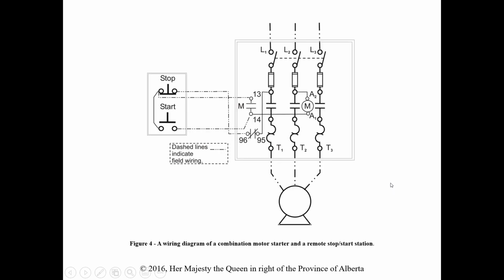Then we talk about a wiring diagram. The difference with a wiring diagram is that it does show some of the detailed wiring for the control devices and equipment. Some individual conductors are shown connecting to specific termination points. Here we're actually seeing a wire connected to this terminal and this terminal. So this is going to tell us how to wire this stuff up. Maybe not show us how things are working, but we know that in this example we go from this point at 13 and go to the stop button. Okay, so that's a wiring diagram.